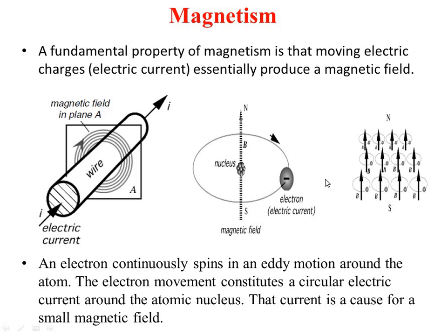Previously, meters used to have a permanent magnet like this, and you might have studied such concepts in your electrical courses. In between, I used to have a coil which carries a current. So a magnetic field was there, and when I pass a current I through this coil, the flux is fixed, this magnetic field is fixed, and I am passing the current through this coil.